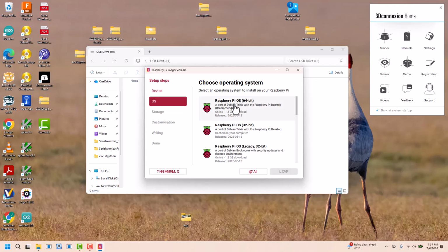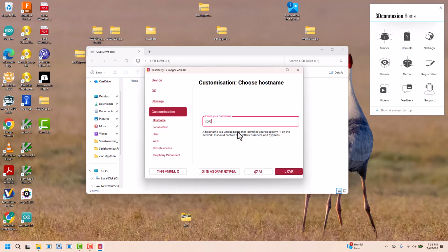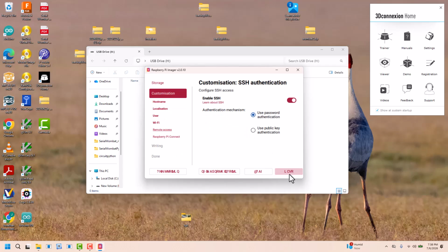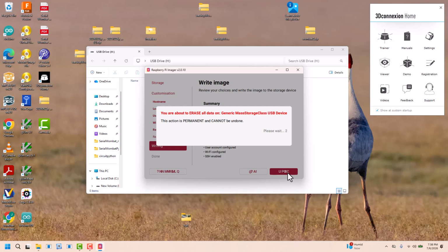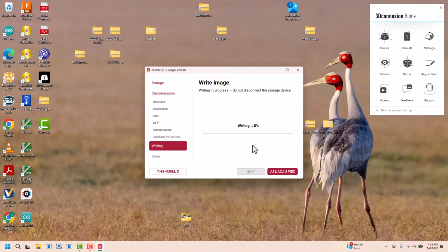The Raspberry Pi 5 is the first of the Raspberry Pi boards which supports I2C clock stretching, which is essential for the proper operation of the Serial Wombat protocol. On prior versions, the chip was made by Broadcom, and they didn't fully implement the I2C spec, and so that meant that there needs to be a workaround. We'll talk about that for the Raspberry Pi 4 and earlier in the next section of the video.